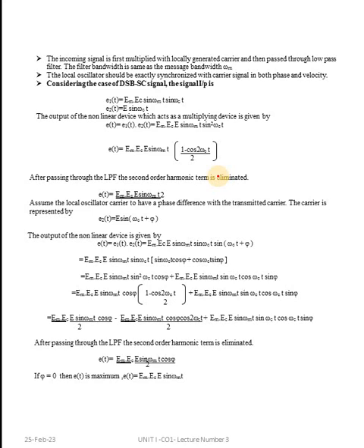So in these two ways we can achieve synchronization. Here we follow the direct apply method, that is, you are directly giving a carrier signal at the receiver end also. Whichever carrier you used on your transmitter side, the same carrier is applied in the receiver also.